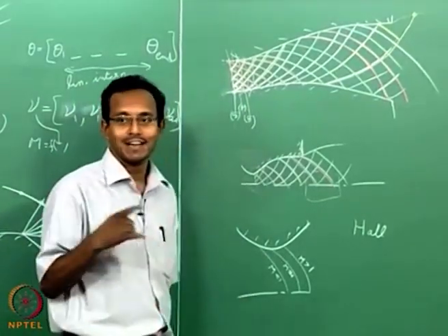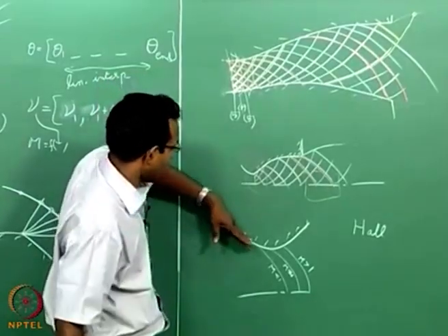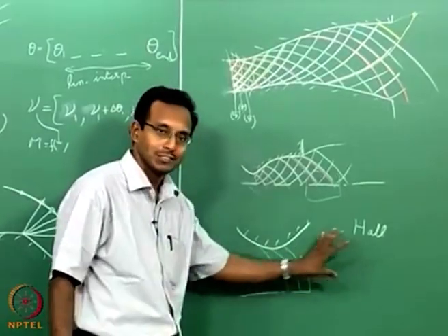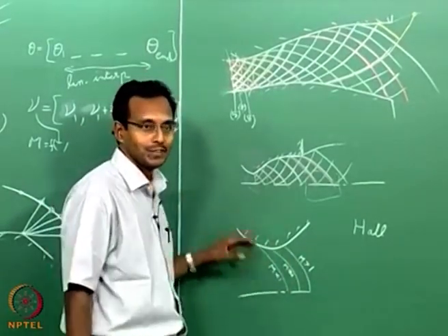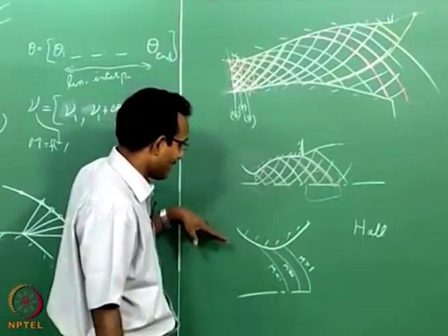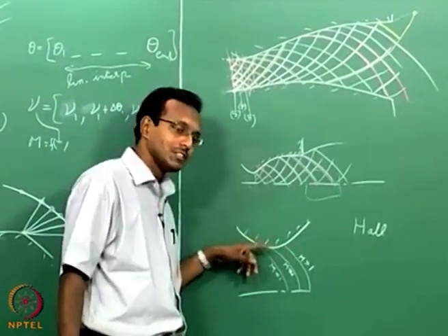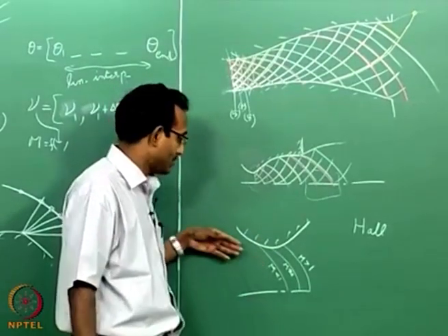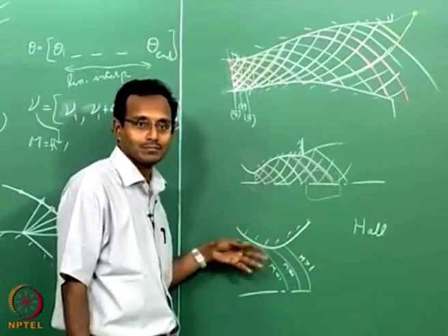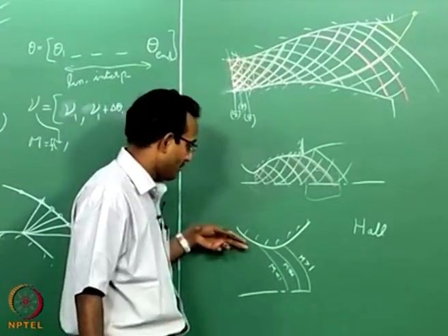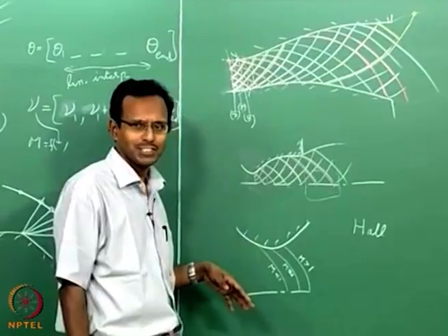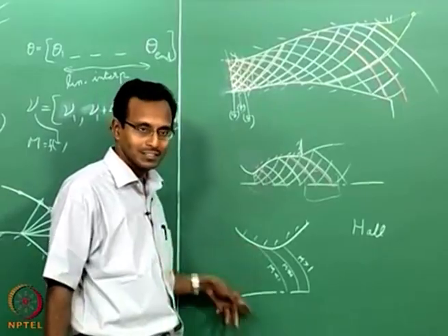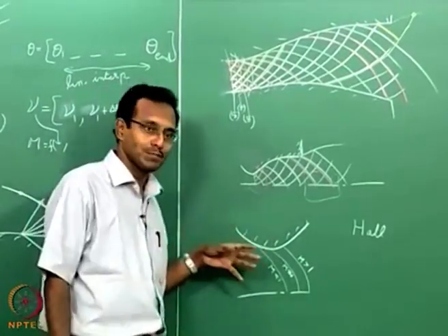It is completely analytical work. What they really did was imagine one cylinder this way, another cylinder this way, and choked flow in between the two cylinders. That is the problem they solved. They have given analytical expressions for velocity, actually they solved for u and v. So from there we can get theta and M if we want. It is not simple, they used series expansion based mathematical methods to solve for this region. The solutions are published already on the web.